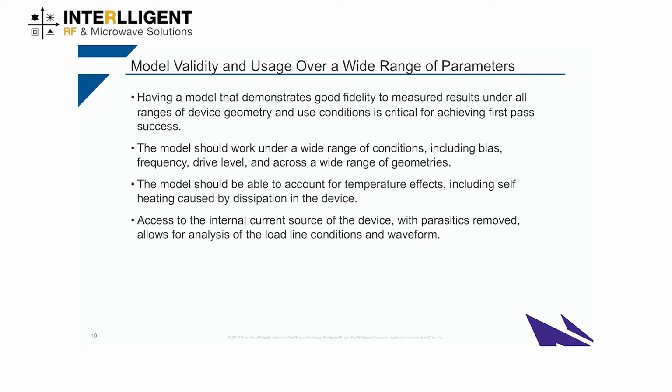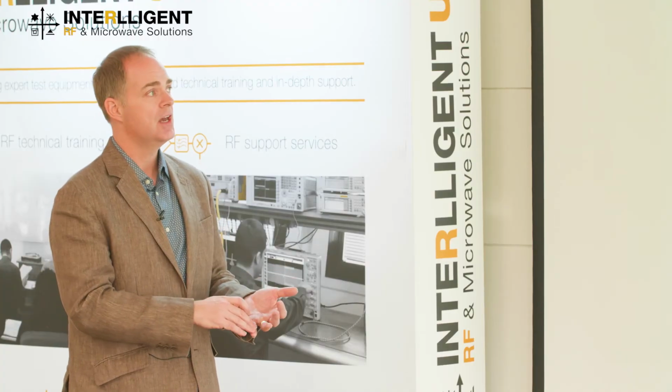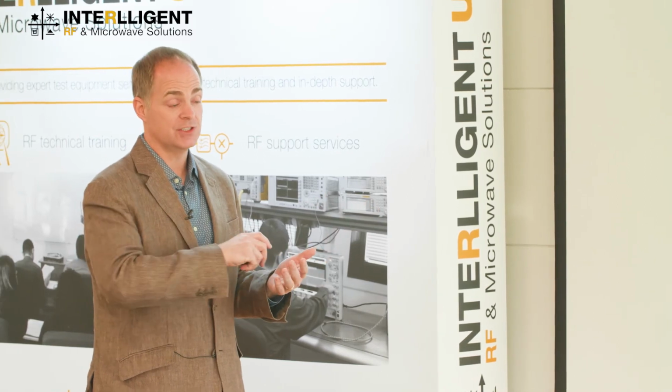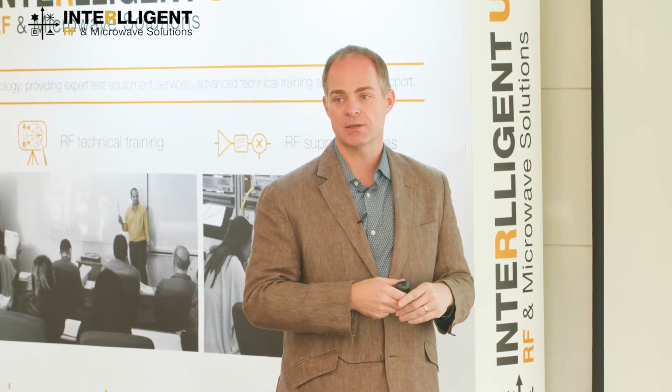So as I mentioned before, if you're looking at this from a design standpoint, one of the most important aspects is how good are my models, right? Model fidelity to what you actually measure is key to getting costs down and getting first pass success on a design. Not only that, but the model should work under a wide range of conditions. So you need something that is going to work at extremely high temperatures across a range of biases and frequency levels and drive levels. It should accurately predict the drive up curve, and you should be able to use it in environments that you may not necessarily be able to measure.